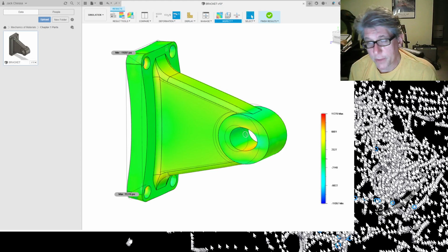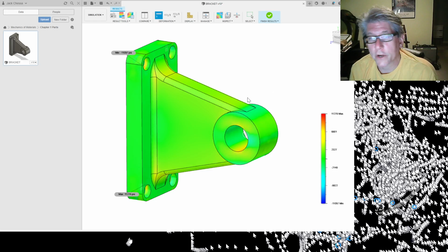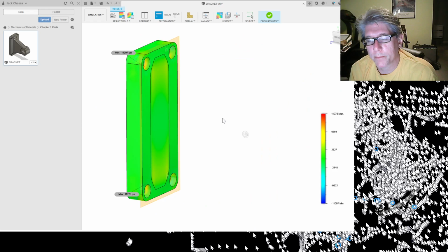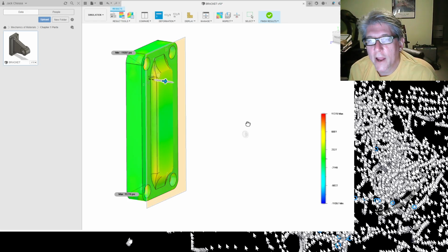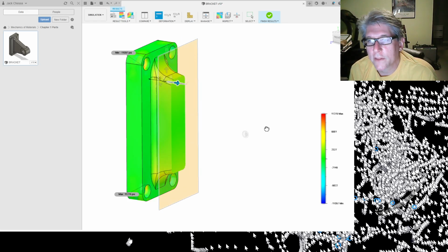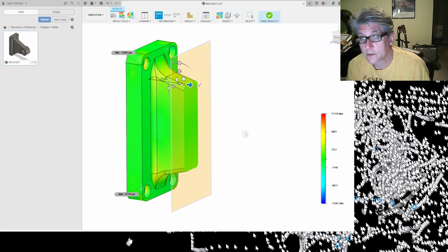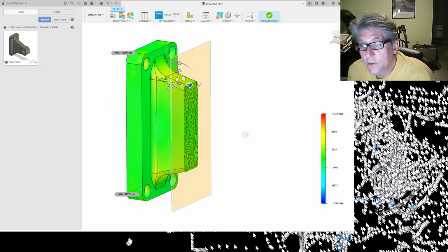So it's going to be under inspect and create slice plane. All right, so we're going to do a plane that's offset from, I asked you to find a cut plane that's 1 inch off of there. So you see, well, here it is. If we drag this little thing, it moves it out in the X direction. And so here it's giving us in millimeters, but I said to do 1 inch off of there, right? So I think we can just type in here 1 inch. And there you go.